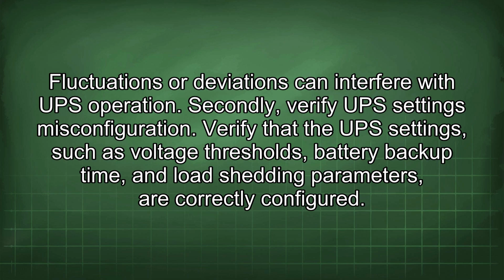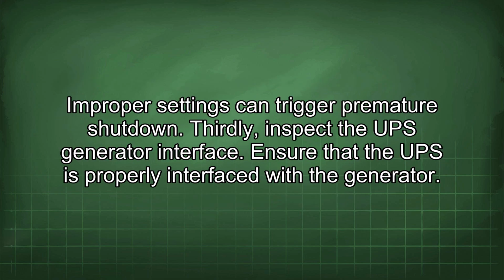Secondly, verify UPS settings misconfiguration. Verify that the UPS settings such as voltage thresholds, battery backup time, and load shedding parameters are correctly configured. Improper settings can trigger premature shutdown.